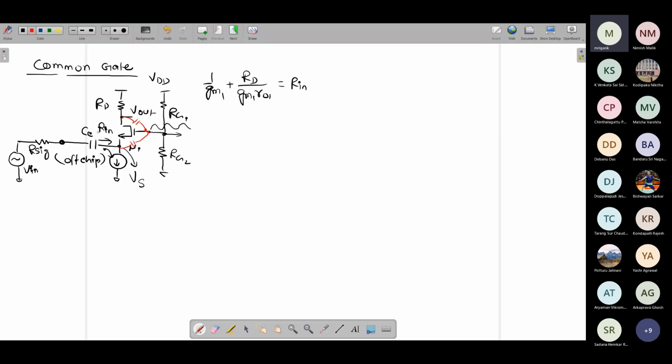Whatever signal you have applied is getting amplified and coming at the source. Here you basically have a high pass filter, just like a CR circuit. Because of this CR combination, you are going to get some finite signal at this node. It is not going to be zero.